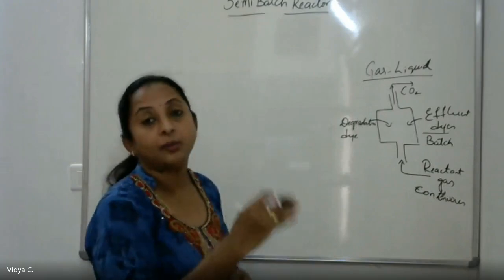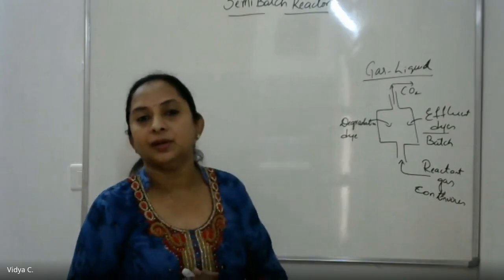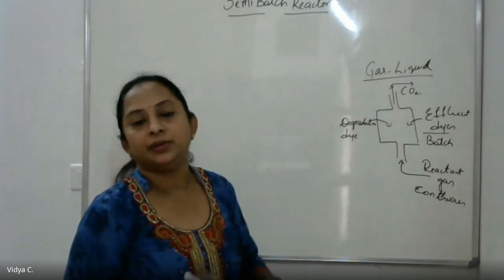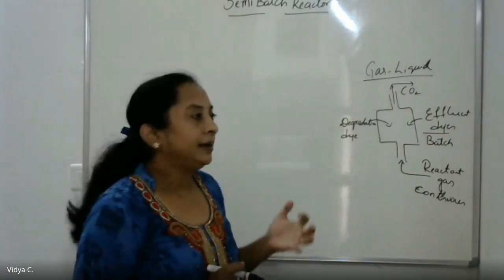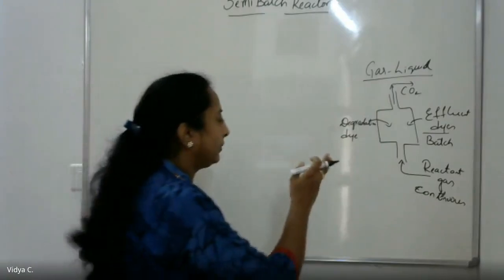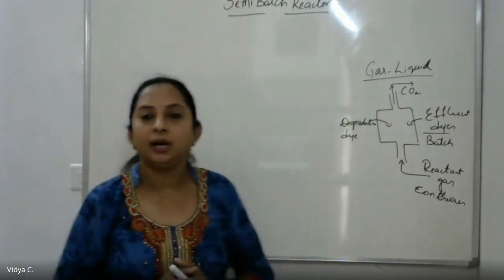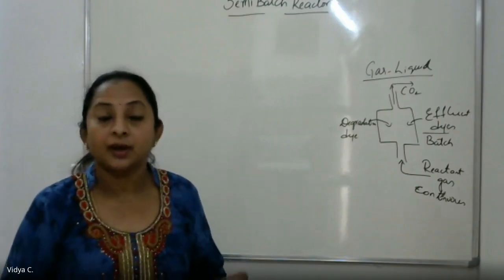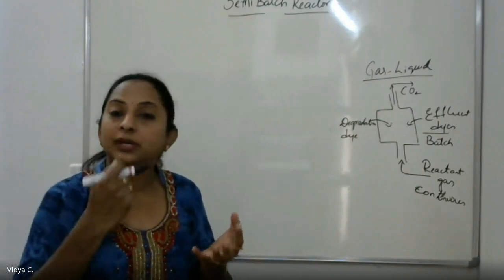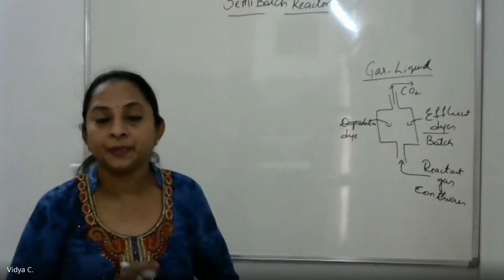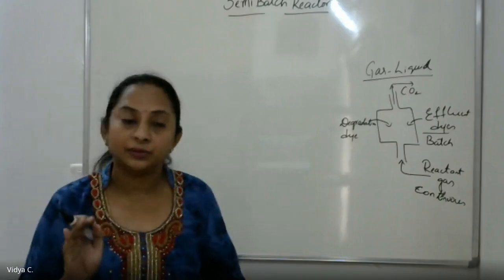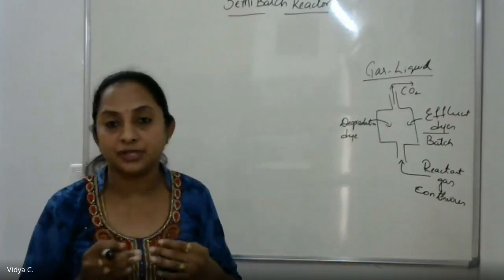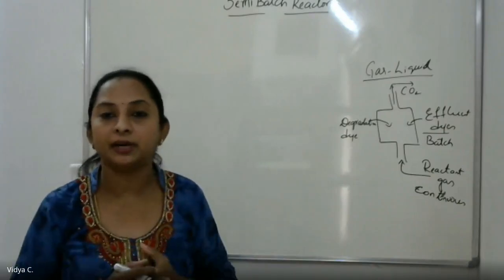These are very commonly used in polymerization reactions and polymerization industries, where monomers are slowly fed into the reaction vessel. And a very important thing: in multiple reactions you would have already studied what a desired product and an undesired product are, and how the reactors are to be connected to get the desired product. There, the selectivity of the desired product is a very important criterion.